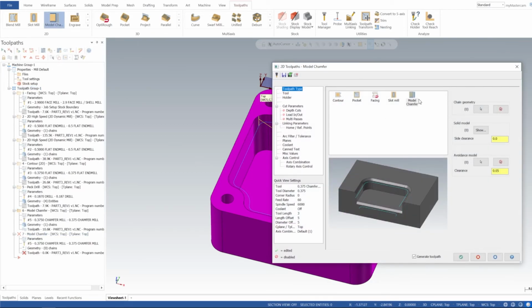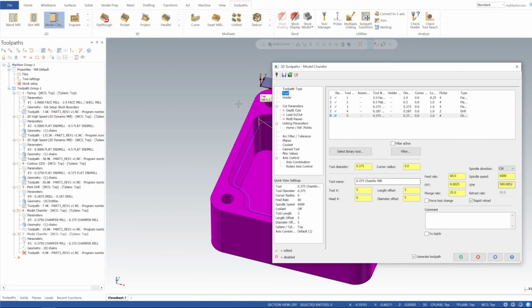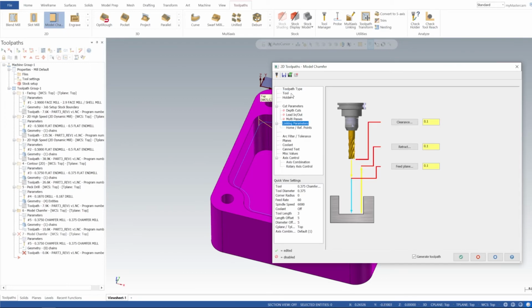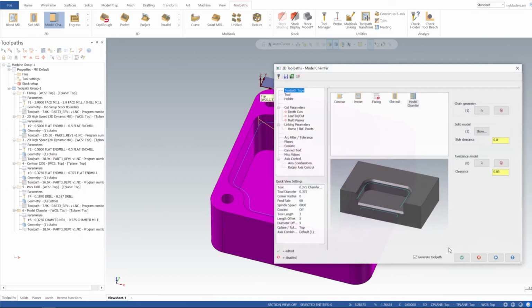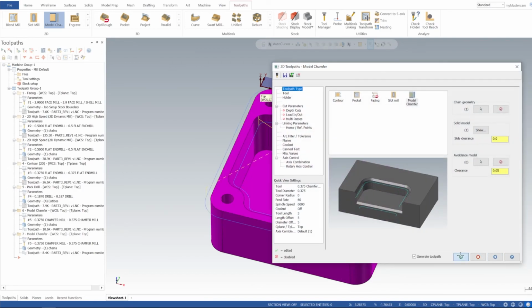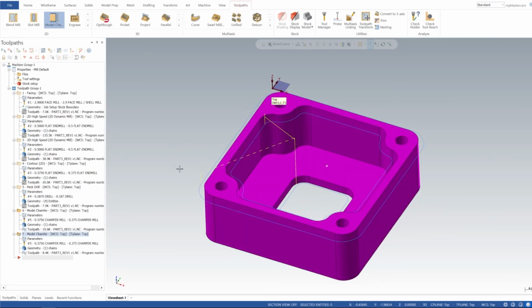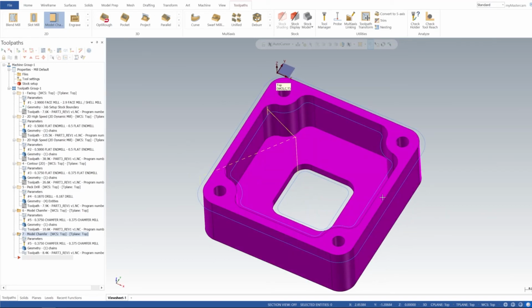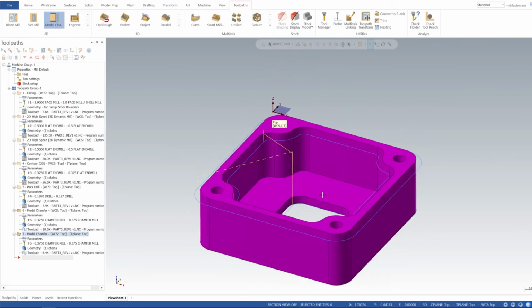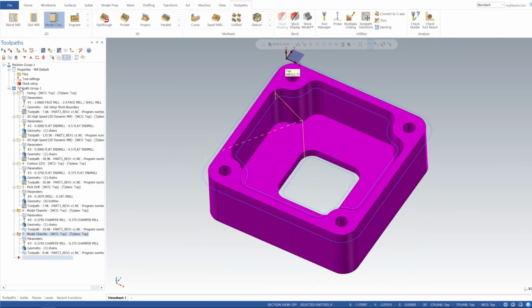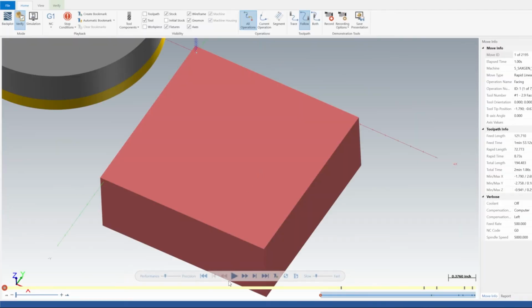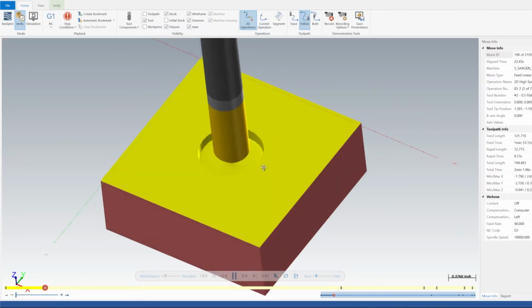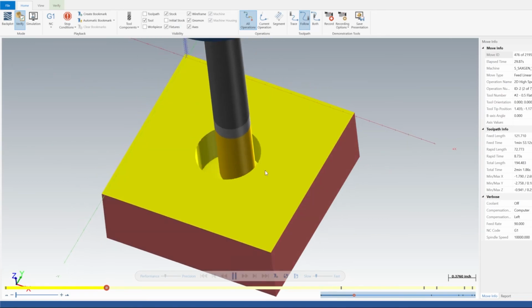But anywho, we could just do another model chamfer and keep all the settings the same. But in geometry chain, we just select the outside. So it's going to do the inside pockets and then do the outside. All right. So now if we go into verify, we should see all that, including our deburring edge break.